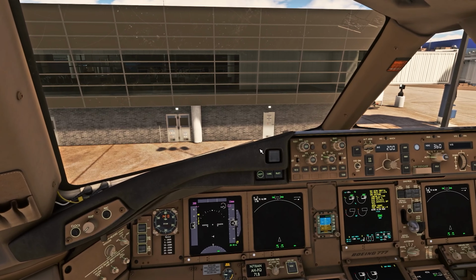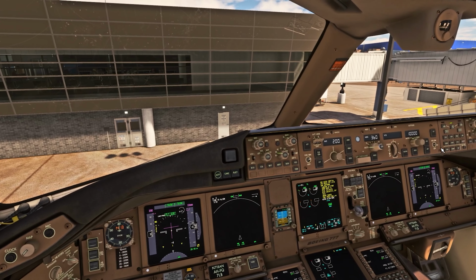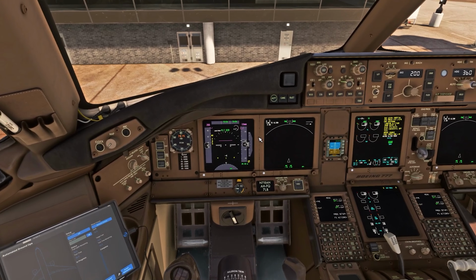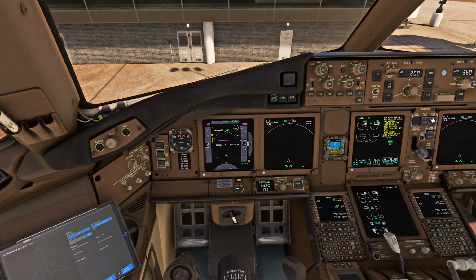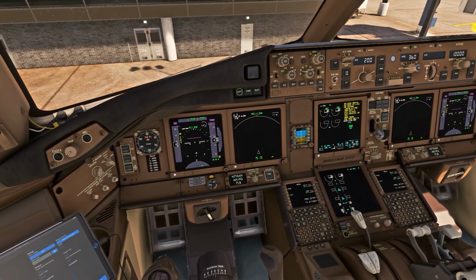So next we're going to go across to our panel here. We're going to turn on our flight directors. You can get your ATC right now, so then you can set your initial altitude and your runway heading. Get that set up. We're going to come down here and look to make sure everything looks good.